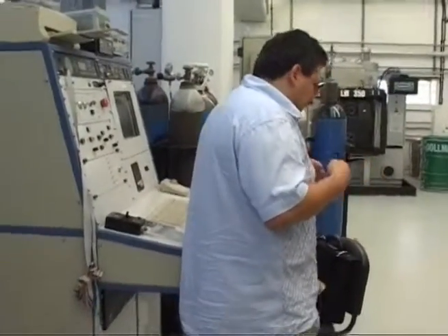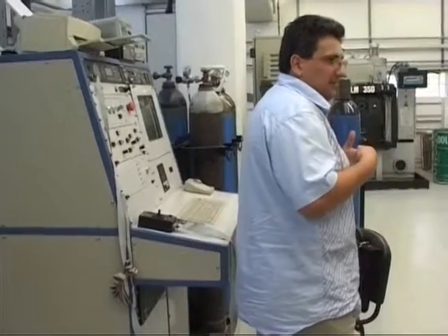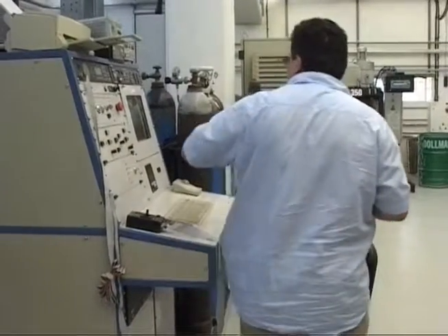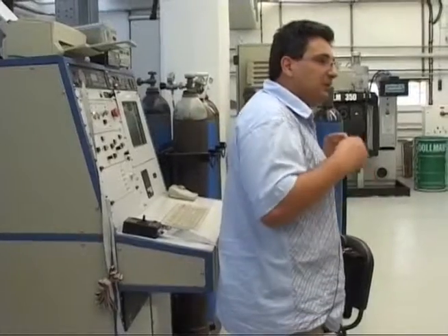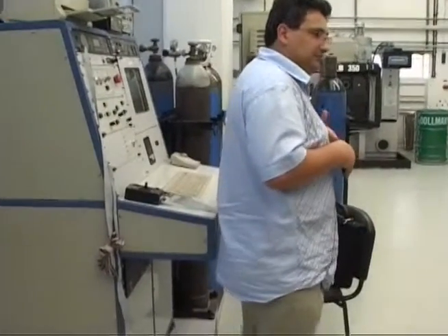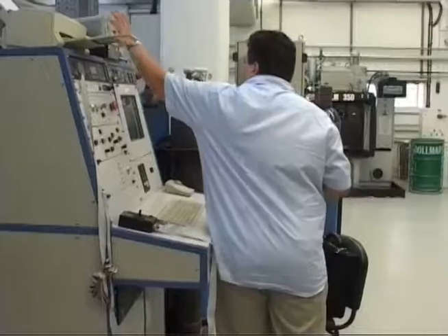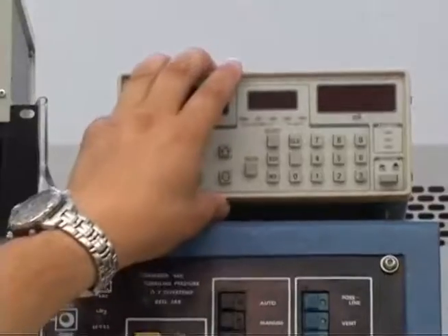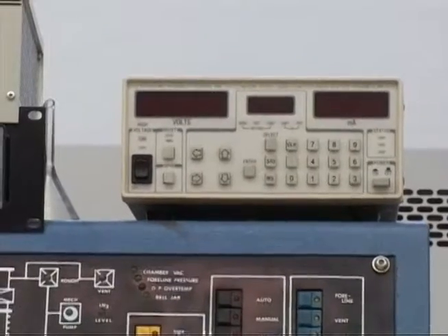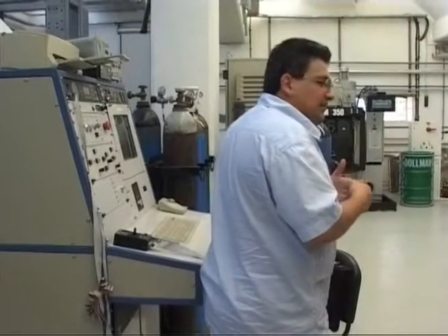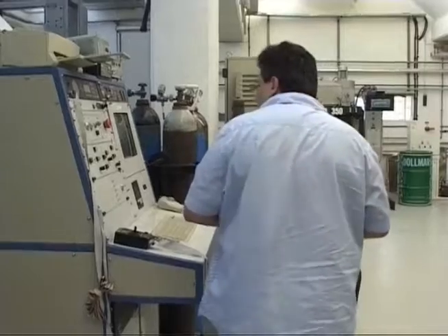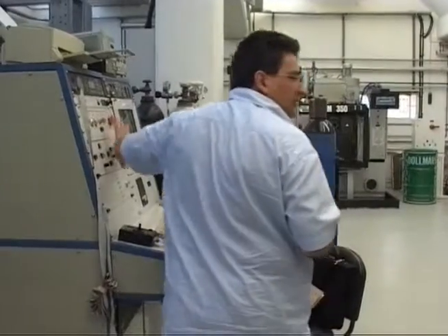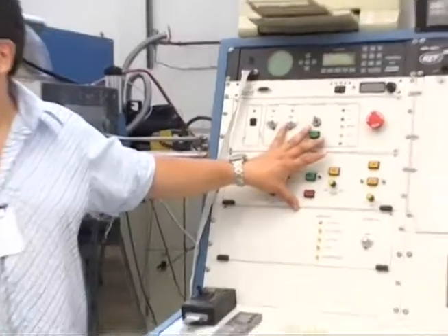It can monitor the rate at which the coating is thickening, and it is so accurate that it can detect one atomic layer at a time. The other components are the vacuum control systems, a high voltage power supply for an eventual substrate biasing, and mechanical manipulation of the components inside the furnace.